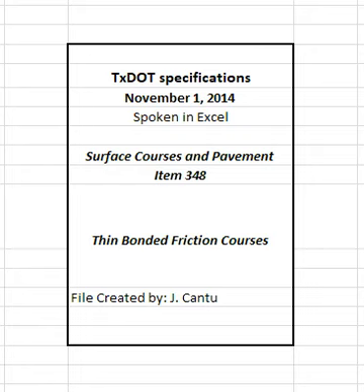4.4.2.1.14 Trial batch testing. Test the trial batch to ensure the mixture produced using the proposed JMF1 meets the mixture requirements in Table 8. Provide the engineer with a copy of the trial batch test results.